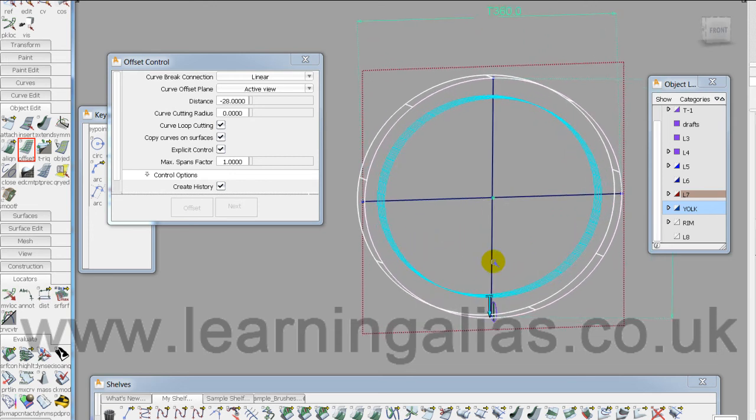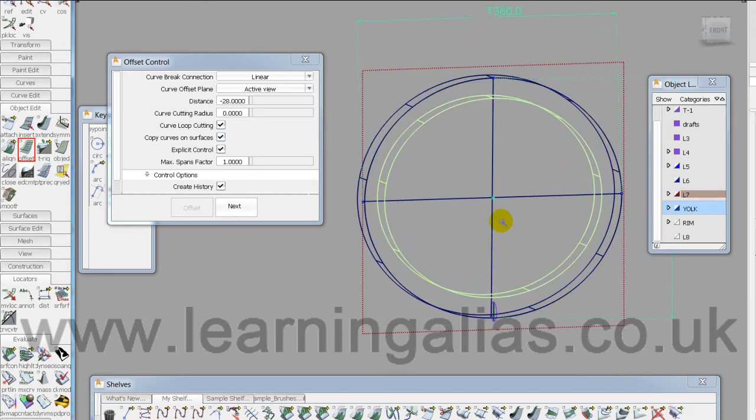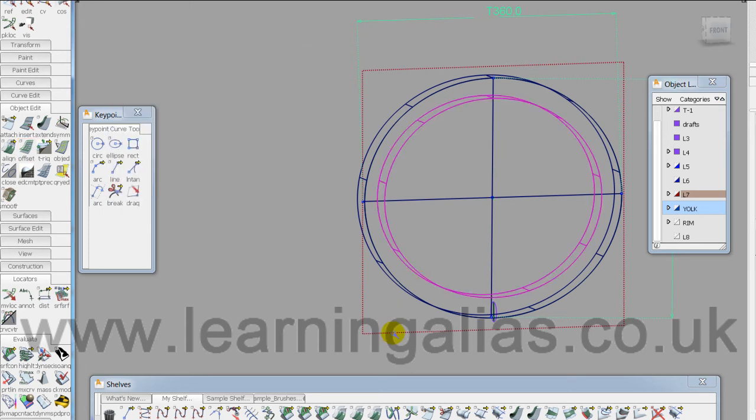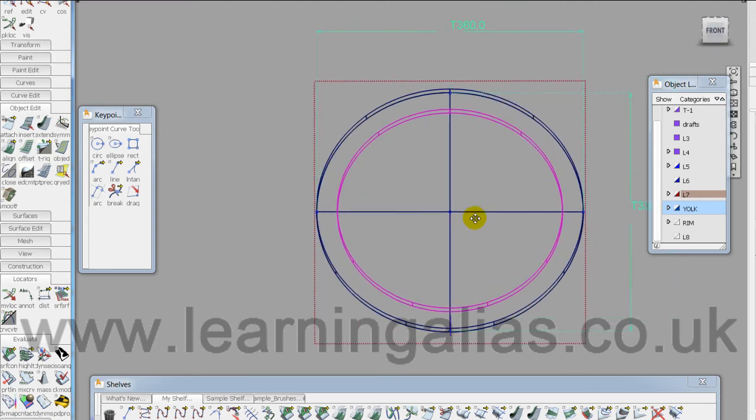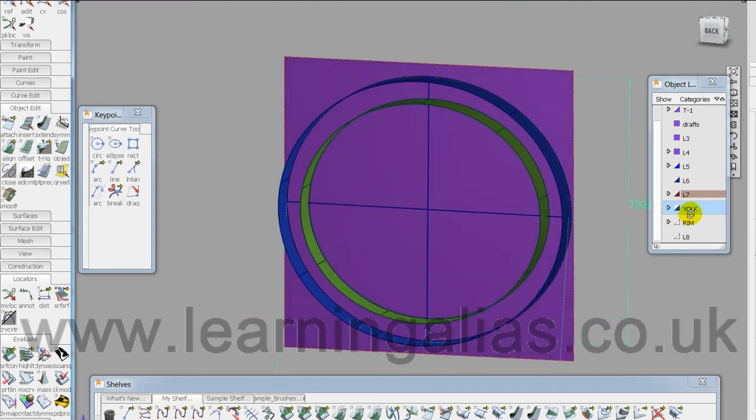surface, and we're going to accept that. Then we're going to use project normal and project the edge of the draft surface back onto this. We'll do that now. For those following my shortcuts, that's Control Q for project normal, and then make sure you pick the 0 edge of the surface, and that gives you a curve on surface. That's the preparation.